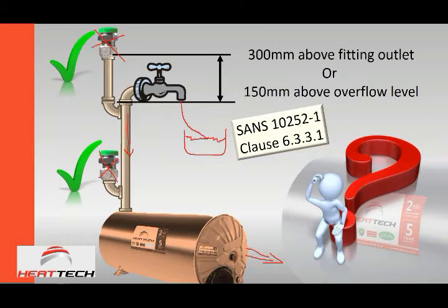And it is important that the complete system must be protected from contamination. Not only the cold water. We make the assumption that only cold water can be consumed, but hot water must also remain protected. You don't know what materials could potentially be sucked up that pipe. The same applies if the geyser is the highest point: exactly the same principle can happen, and if the air is not let in, water can be sucked from the wrong side into the geyser as well.